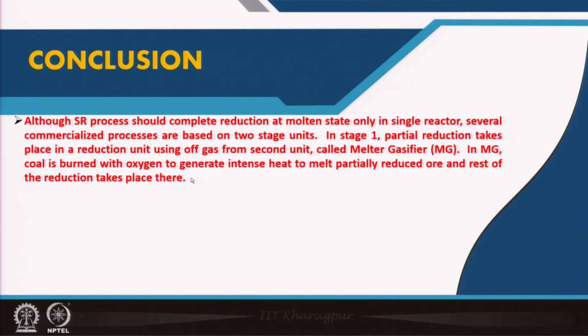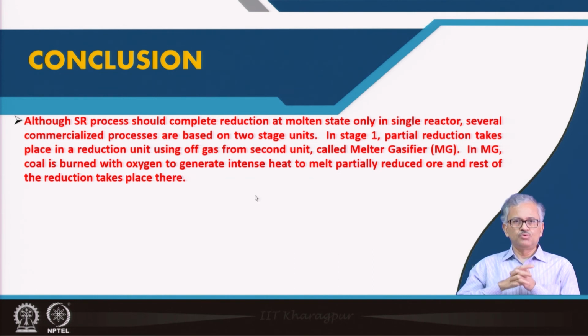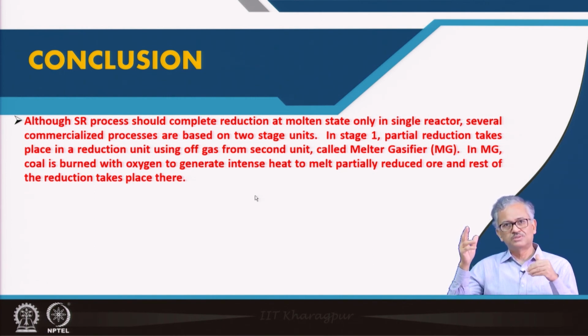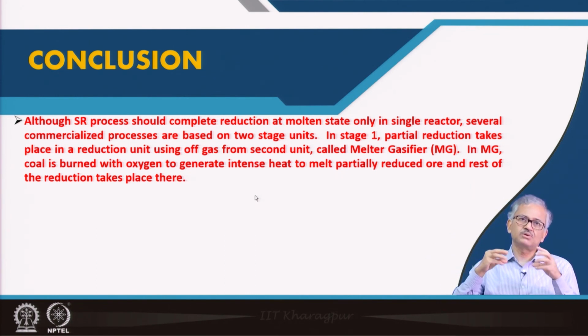So in conclusion, what you see is the ASR process. The ASR process was basically developed to avoid the problems of the DR process, like accretion formation and sticking of the pellets. It can also be compared with the blast furnace, because the products of the ASR process and the blast furnace are both hot metal of almost similar quality, and sometimes ASR hot metal is better than that of the blast furnace.